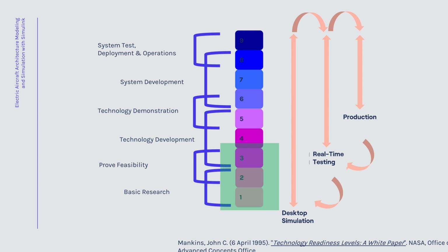For example, you may incorporate models of actual technology types such as PMSM with field-oriented control, but at the medium fidelity stage, you may still not have vendor-specific information on physical components and control components. A high-fidelity simulation model would have vendor-specific architecture, including parameterization of physical components and control system architectures. The model could also include detailed power electronics, thermal and cooling systems, and communication protocols.